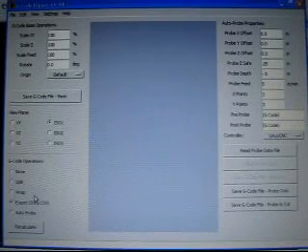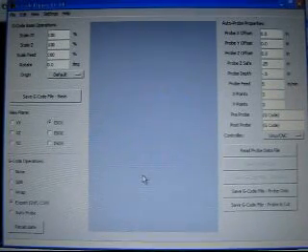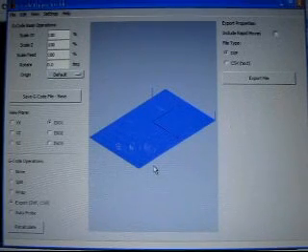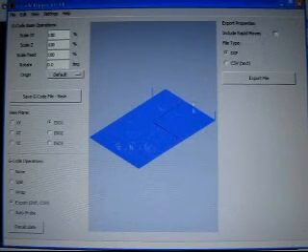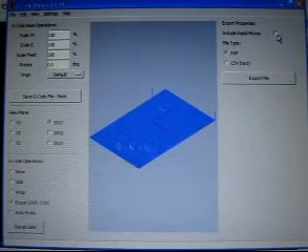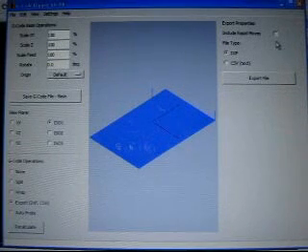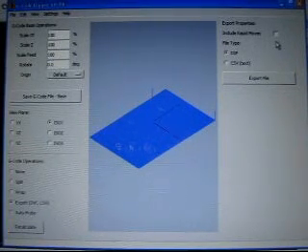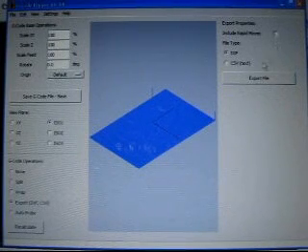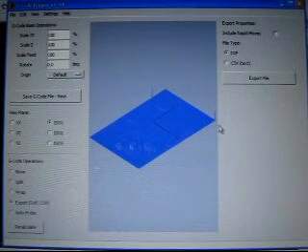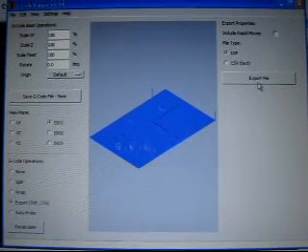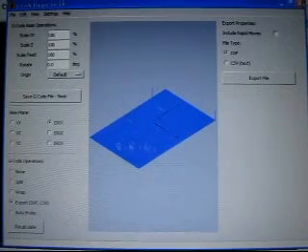And then this is what I use it for most of the time, is to just convert my G-code into a DXF file. So all you got to do is set this up. I set not to include any rapid motions, but it will export them on a separate layer for you if you do include it. But that's it. I'll just go ahead and export this file and bring it into the next program. Okay, so save that as a DXF and then open it in this program right here, DoubleCAD.